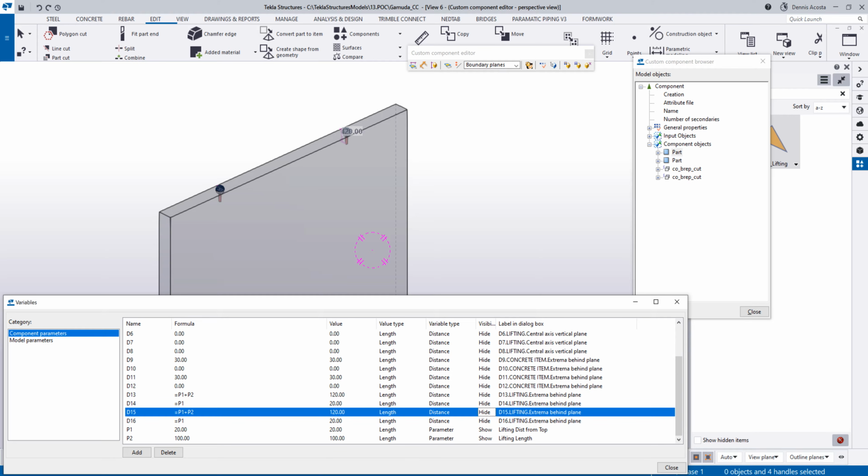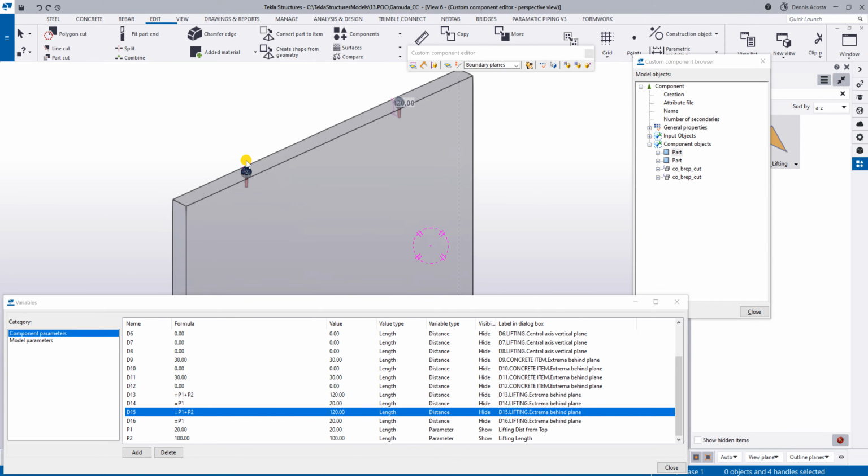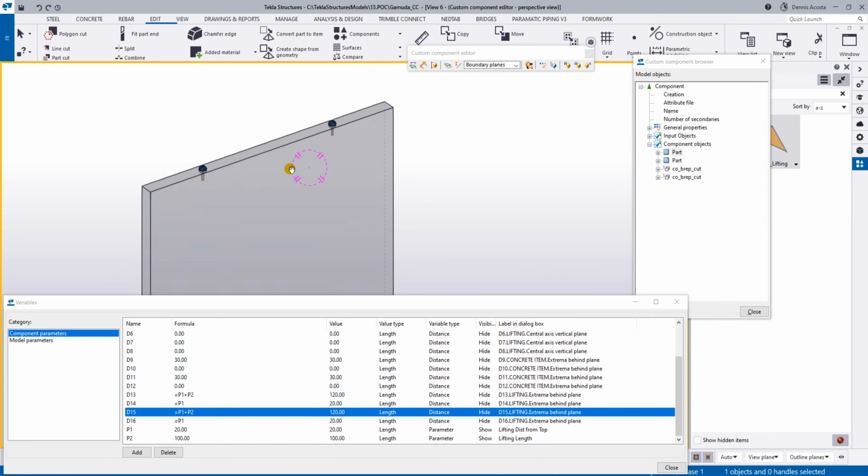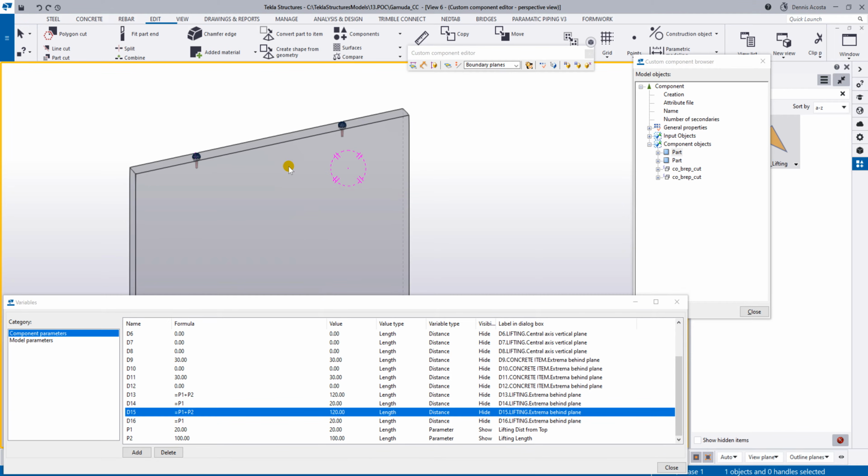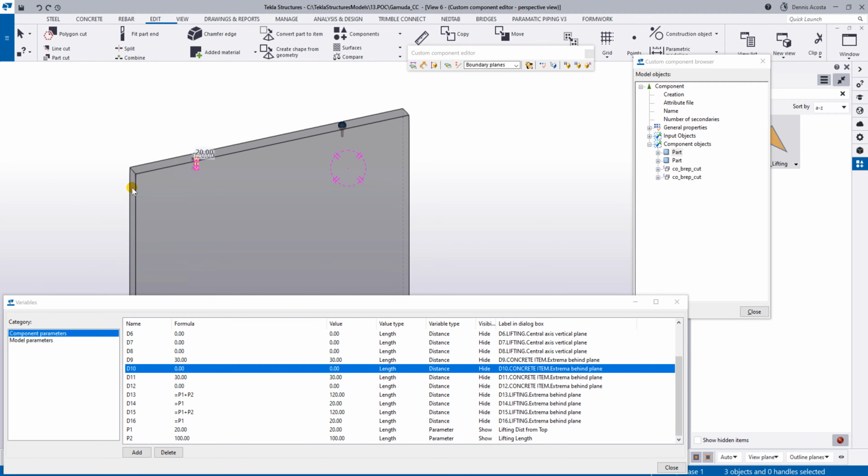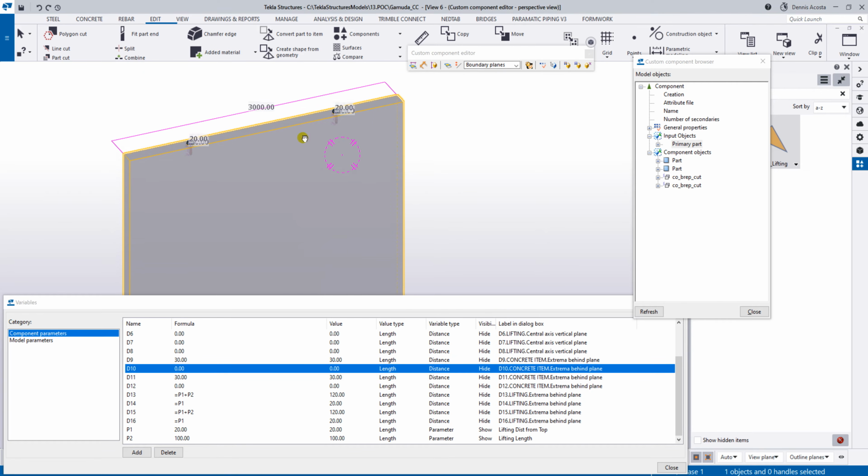Okay, so now the question here is, do you want to automate this one or do you want to control the size? The reason why I ask, it depends on you. Controlling the size meaning I can select this one and then bind it here to the size and put the dimension. Usually lifting is automatically assigned according to the panel's CG. Yes, that's right.